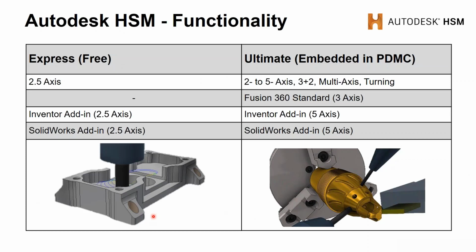Also, there is a free version of HSM. If you have an Inventor LT license, you can download HSM Express for free. But that is only 2.5-axis machining, so no turning and no 3D machining. And of course, that could be done also for SolidWorks.